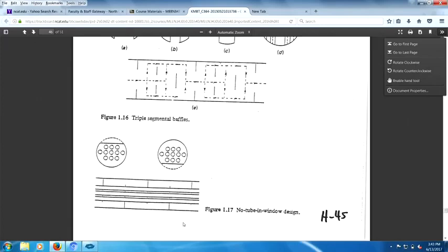Anyway, a place for good vibrations. A Beach Boy song with vibrations. So we have the tube sheet, tube window, right? We have tubes through. We don't have any tubes in the window because if they were there, they'd be vibrating. That's not good.